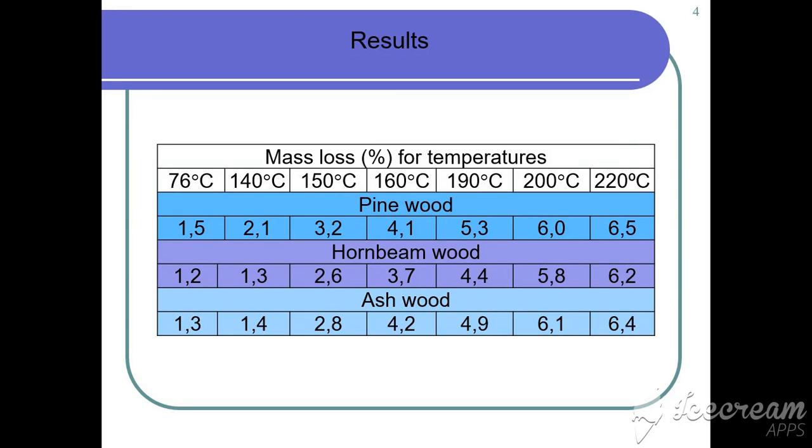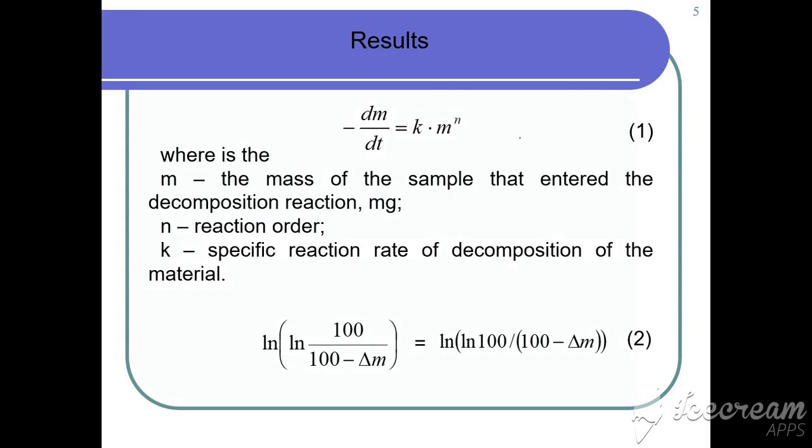In the studied wood sample at temperatures from 75 to 100 degrees, endothermic processes take place, which are accompanied by a loss of up to 6% of their mass. The main increase in weight loss occurred in the temperature range from 180 to 220 degrees, due to the extractives of water and ethanol, as a result of polysaccharide degradation. Thus, the thermogravimetric parameters enable us to determine the rate of thermal decomposition of the material at a given temperature and therefore show a qualitative assessment of the effects of heat.